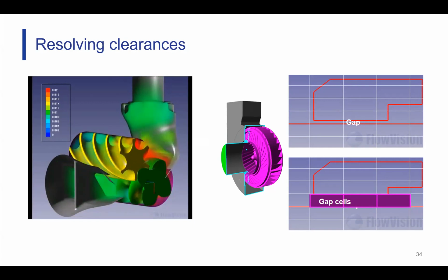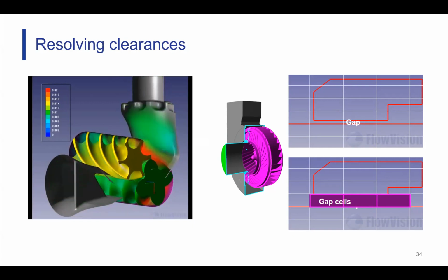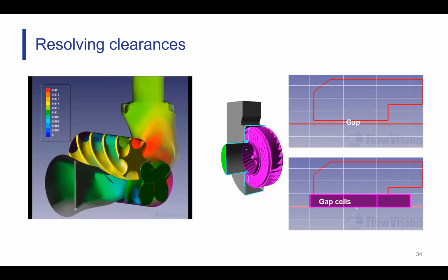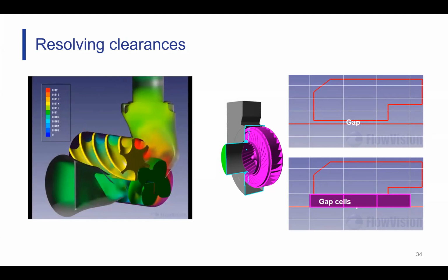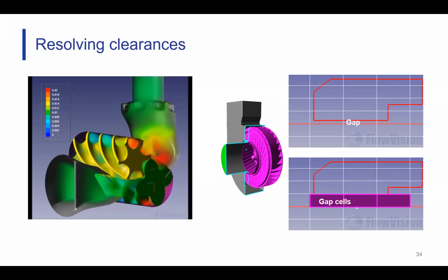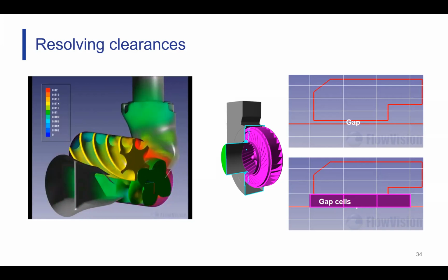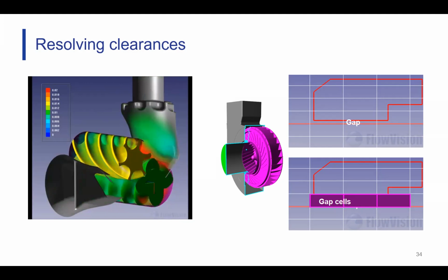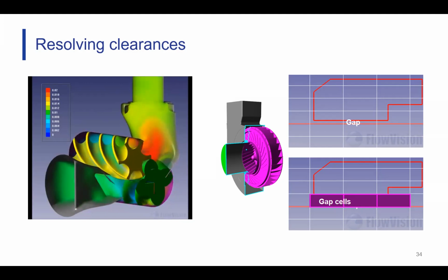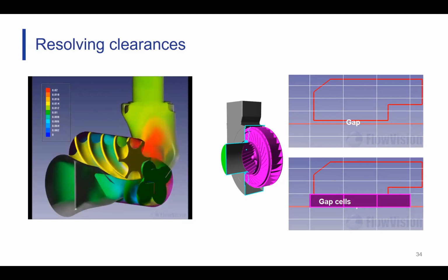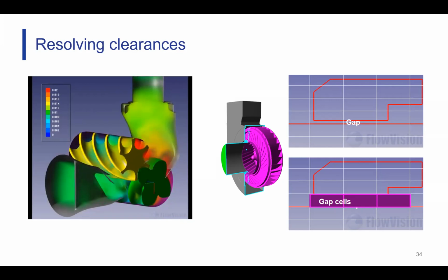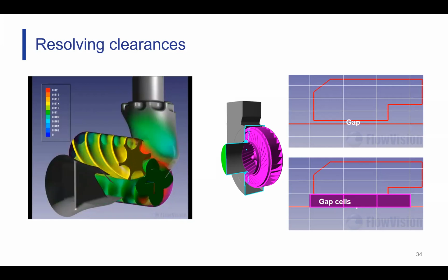Again, all the user needs to do to apply this, you perform your initial meshing as usual, and then just enable the gap model. That's all you need to do. Specify the threshold for clearances and count it in the calculation, enable the model, and that's it. FlowVision will then automatically identify the necessary cells and apply modified governing equation to those areas. This helps you retain full accuracy of your solution with pretty much no increase to the workflow or to the calculation time.